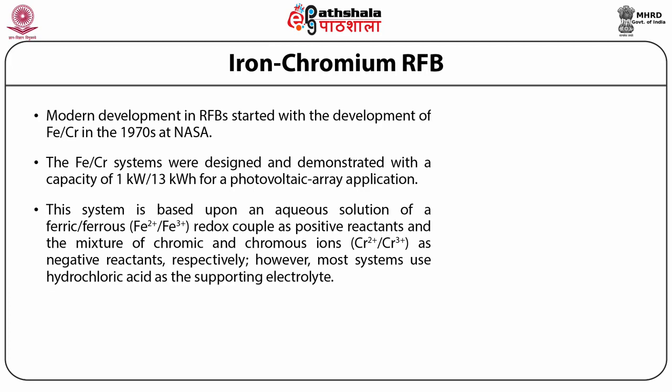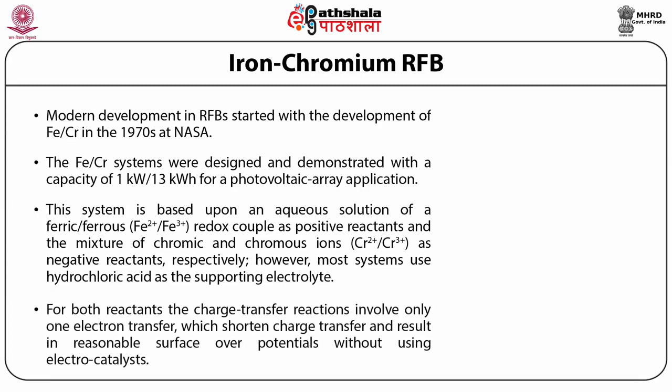Iron-Chromium RFB system can function with an IEM and low-cost carbon felt electrodes. For both reactants, the charge transfer reactions involve only one electron transfer, which shortens the charge transfer and results in reasonable surface overpotentials without using electrocatalyst.